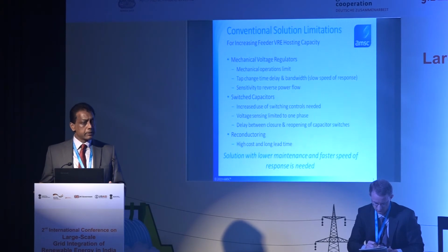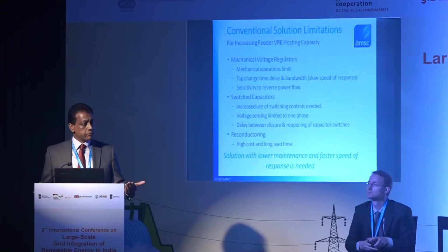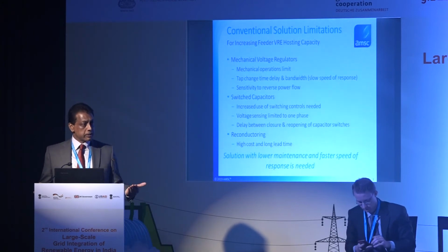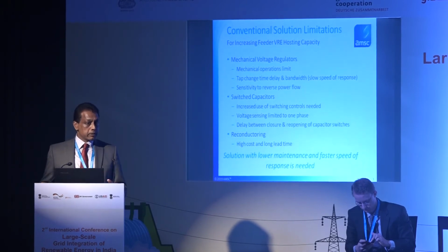Also, with cap banks, once you switch them in, and then if you don't need it, you switch it out, typically you have to let it discharge. So in other words, there's a waiting period before you can bring those cap banks in. And those types of limitations do not help your whole cause of having more variable generation on the grid.